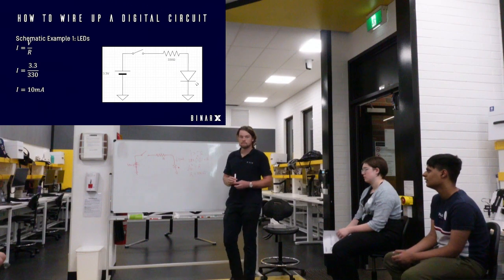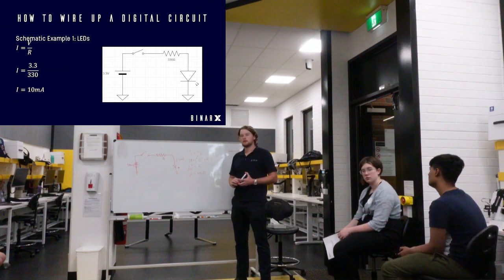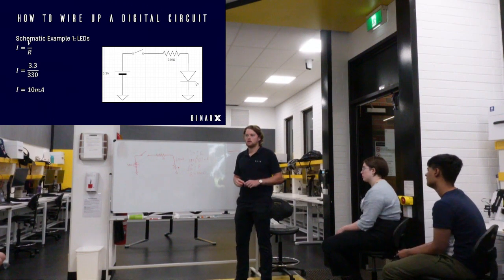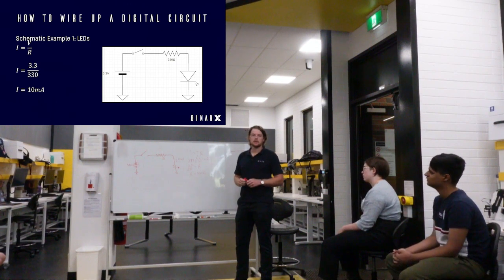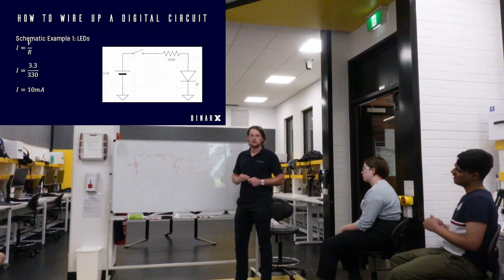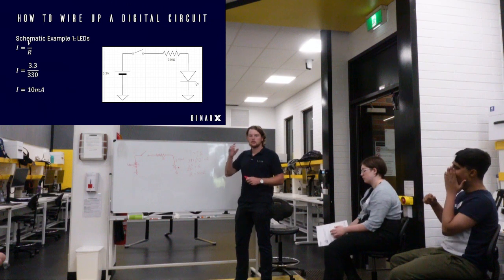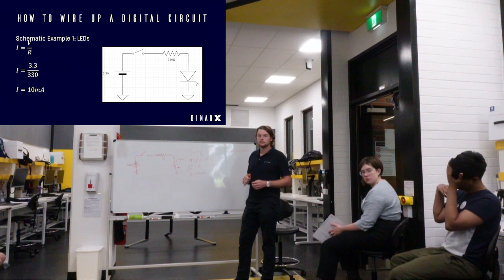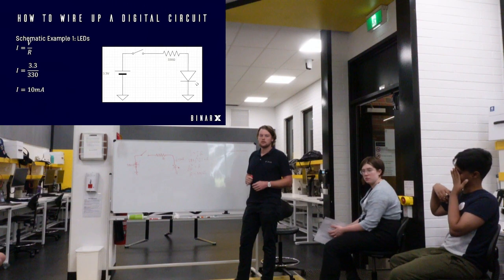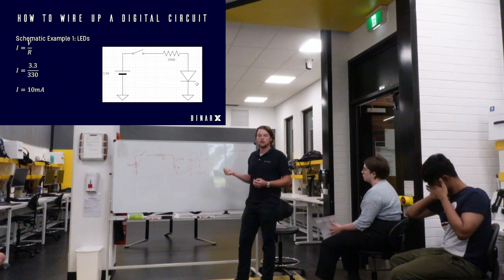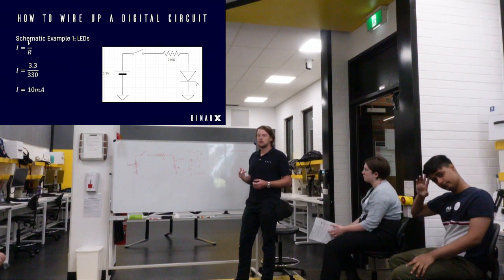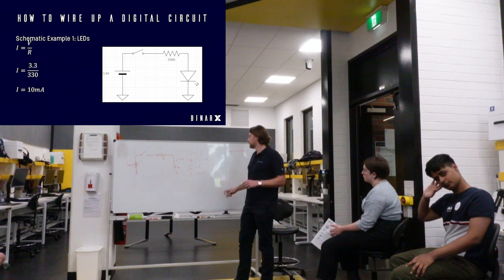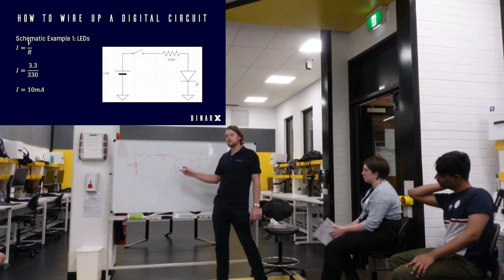And that would be if there was no voltage drop across the diode, right? Assuming ideal diodes for this case. Are you going to talk about taking into account the forward voltage of the LED in a second? Do you want me to? They're going to need to do that. So maybe you can show how the equations change when you take into account the forward voltage drop of the diode. Do you know what the forward voltage drop of your diodes is?